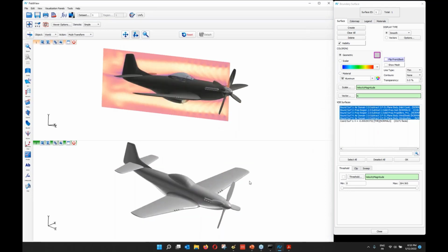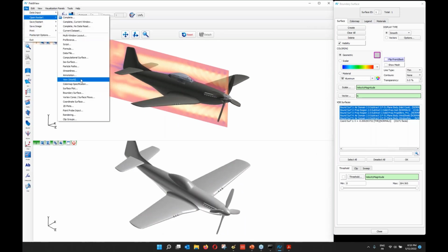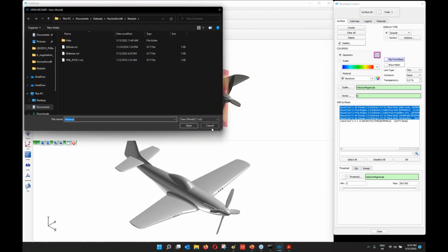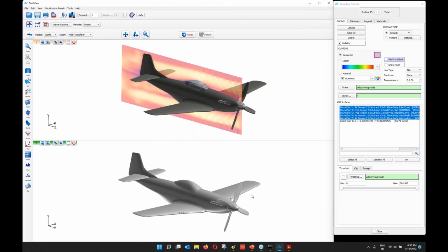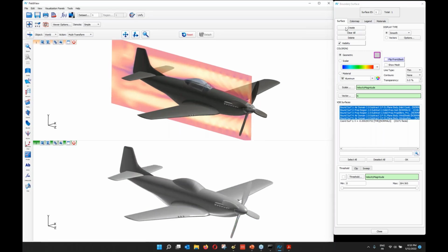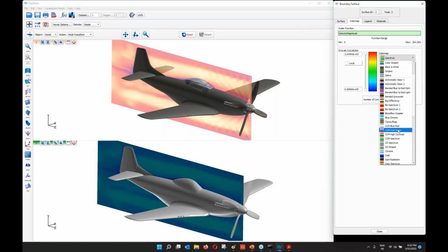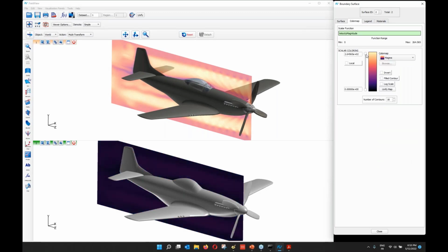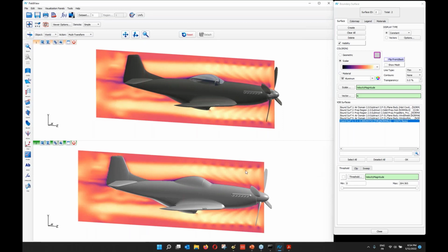You can see that I didn't start from the same view. So what we'll do is open a view, restart at the bottom. Or even easier, we'll do a reset. Okay, that's better for synchronizing the views. Over here I have the velocity magnitude, that's not a very good pick. I should have exported pressure as well. But if I create a second surface for my cut, on that one, I can look at velocity. And if I pick the same color map and adjust the range.